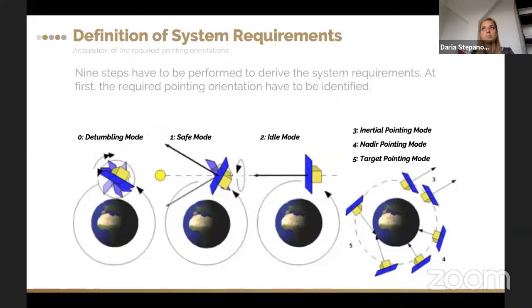However, instrumentation for these high-speed bands is already much more complicated, and especially antenna design is much more complicated. In X-band and S-band we can still use patch antennas or helix antennas, but K-band requires additional investigation.